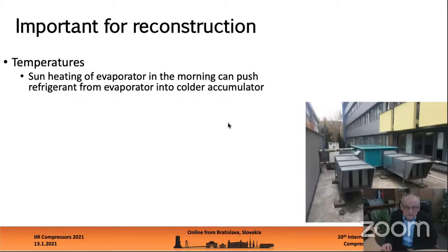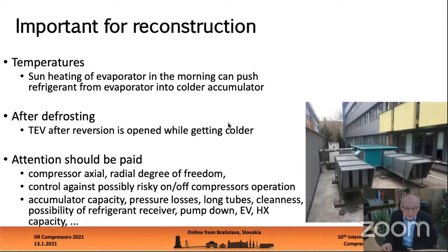Important for reconstruction. Important is to follow temperature. For example, sun heating of the evaporator in the morning can push refrigerant from the evaporator into the colder accumulator. After defrosting, the thermostatic expansion valve is open while getting colder.